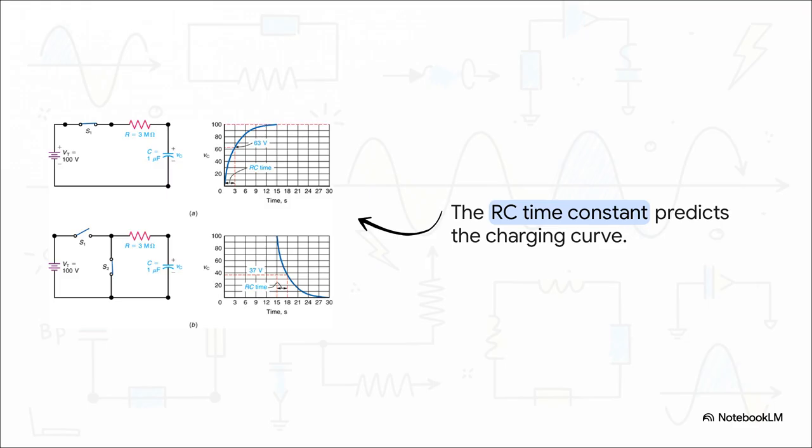Exactly one of these so-called time constants represents the specific moment the voltage reaches exactly 63.2% of its maximum value during its initial rise. Now, why 63.2? Well, that specific percentage isn't random. It's derived purely from Euler's number in mathematics, which represents the natural rate of exponential growth and decay in the universe. It's almost like a universal speed limit. It takes exactly 5 of these naturally derived time constants for the capacitor to reach 99%, which is essentially a full stable charge.